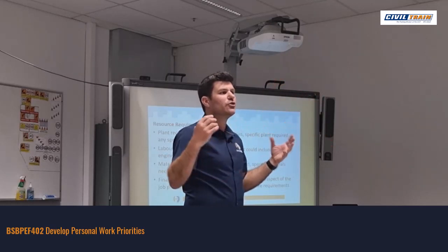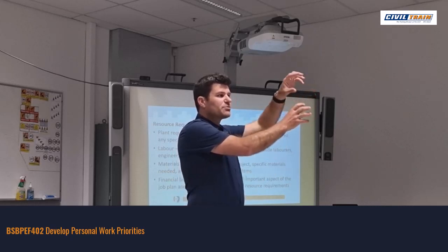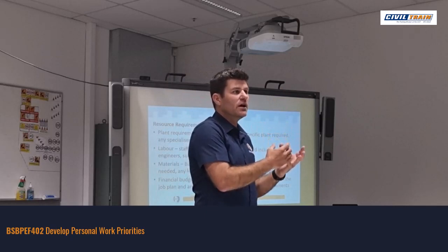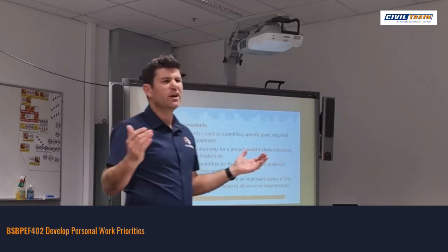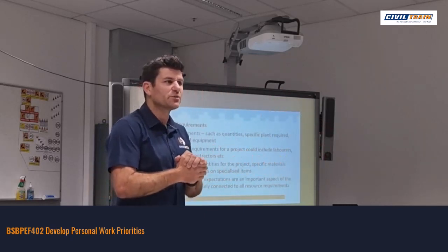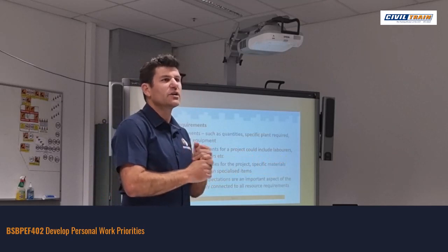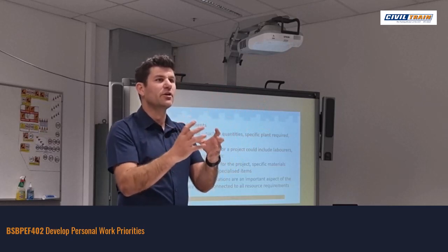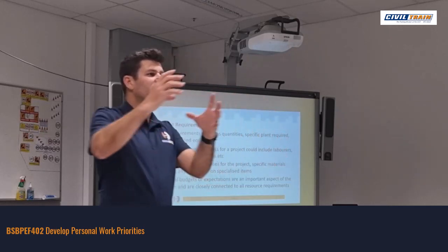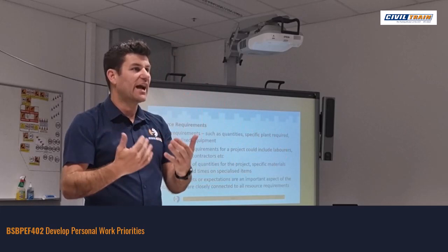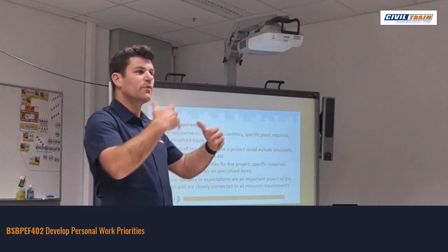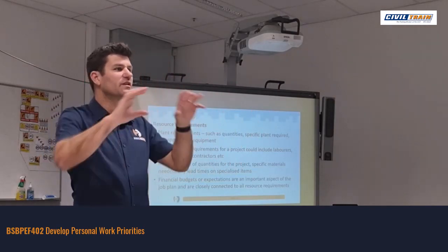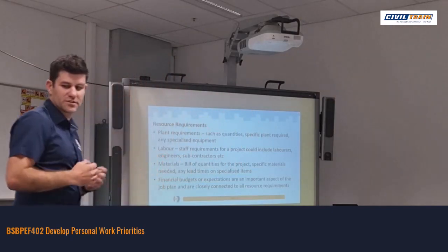But it's a lot of human resources to do that. If I was to spread those activities out, I could potentially use less people, but still complete it within the same time frame. So sometimes we talk about being resource dependent and also leveling off, where we try and move activities that don't need to be completed on day 1 and move them to a day where we've got minimal activity happening. So we keep the work crew busy throughout the program, but we actually start moving things around. So we'll be looking at that process as well.